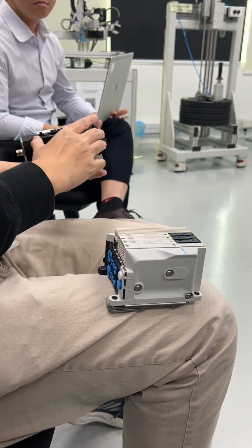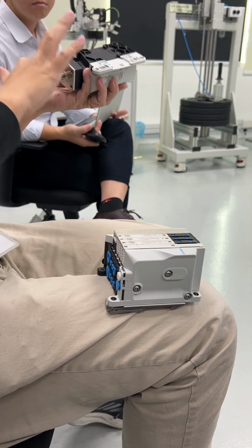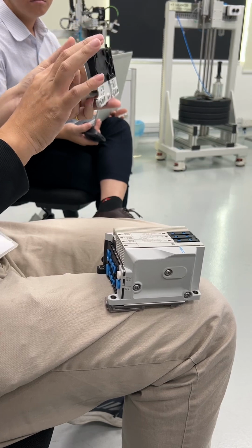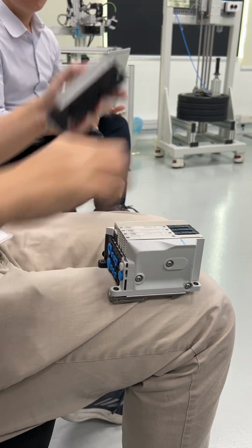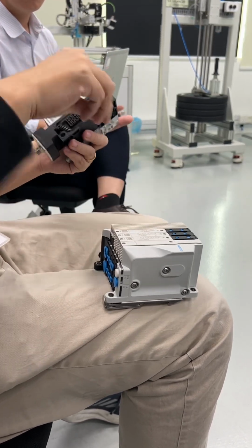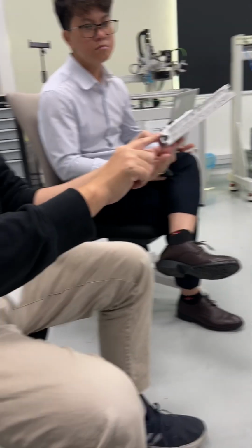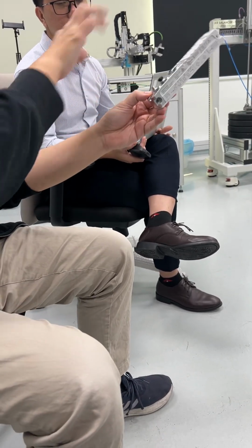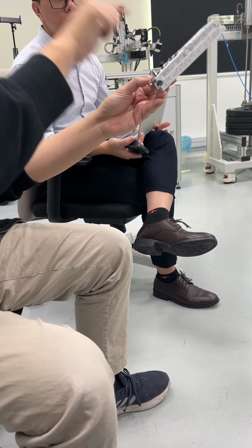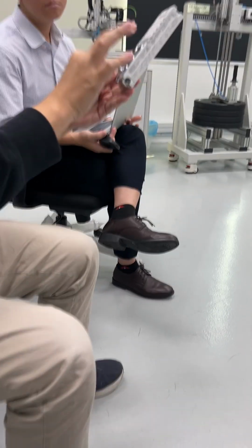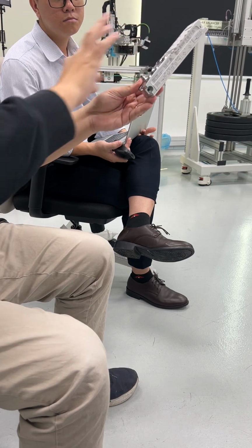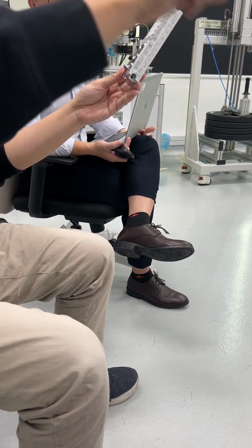This is the sub base with power supply, but most of the sub bases are without this big thing here. Later you can see that it's just a flat one, like something like this. So those are without power supply. But for CPX-AP-I, each of the modules has a power supply port. So of course you can loop the power supply from this module to another module. But you can also have an individual supply for each. Like this module, you add a power supply here, and this module you have another power supply.